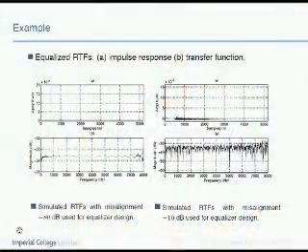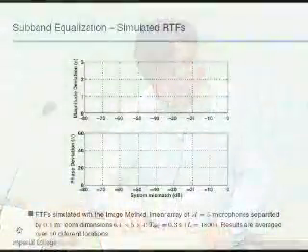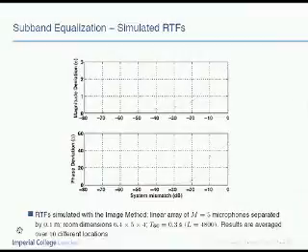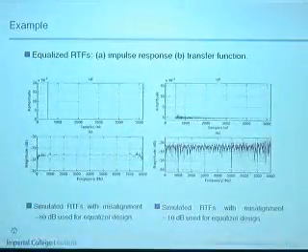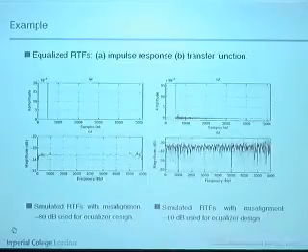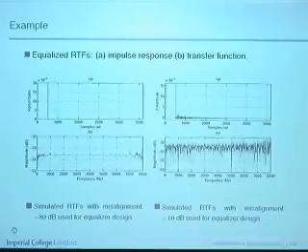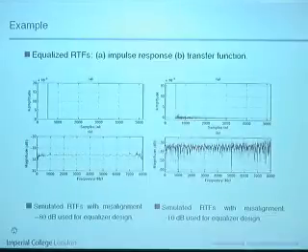And I'll just show you a couple of examples, one case when you're here and one case when you're here, so that you can see what the output looks like. So here is the impulse response of the output with nearly noise-free estimates of your impulse responses. And here is the magnitude. So you can see that it's pretty well equalized. On the other hand, when you have the minus 10 dB misalignment, you start to get some rubbish in the equalized output.